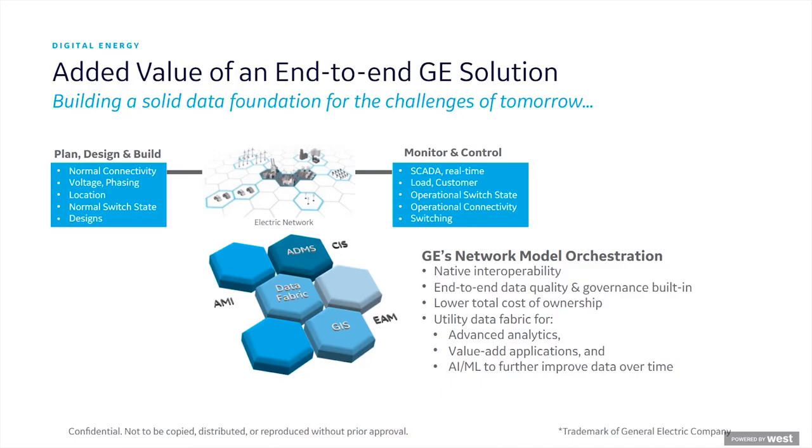Yeah, so within the workflow on the GIS, we've got patching available in our network. So patching goes the other way around. It comes from your GIS to your DMS, not from your DMS to your GIS. So yeah, that's right. The network model changes are made in the GIS and propagated as a patch into the DMS.